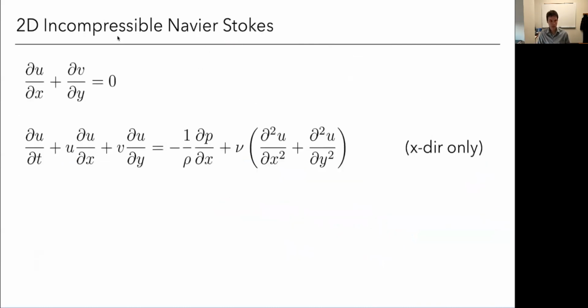Okay, so let's now take what we've learned here and apply this to an example. In this case, this is just a motivating example that applies in general to Navier-Stokes equations, but just for simplicity in writing things out, we'll just reduce it to the two-dimensional case and make it incompressible. But again, the same concept will apply for 3D compressible. Okay, so here's those incompressible Navier-Stokes equations. What we're going to do is plug in all of those variables, right? So we'll plug in U is U plus U prime, and P is P average plus P prime, and so on. So far, doing that, no approximation is introduced.